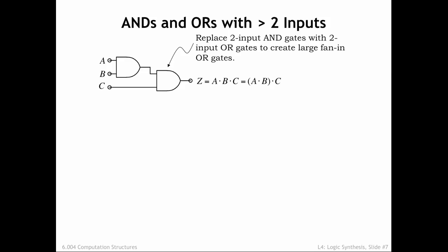The approach shown here relies on the associative property of the AND operator. This means we can perform an n-way AND by doing pairwise ANDs in any convenient order. The OR and XOR operations are also associative, so the same approach will work for designing wide OR and XOR circuits from the corresponding 2-input gate. Simply substitute 2-input OR gates or 2-input XOR gates for the 2-input AND gates shown below, and you're good to go.